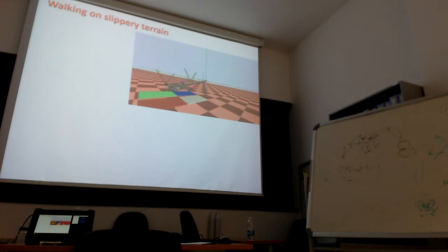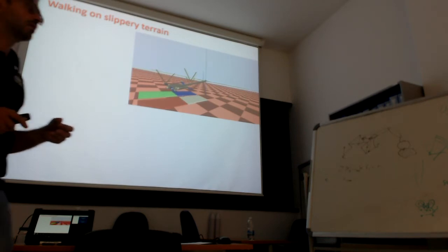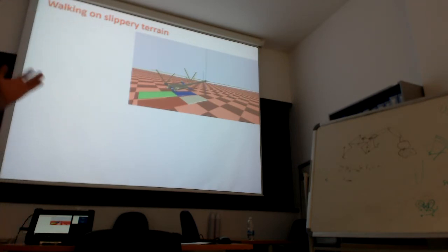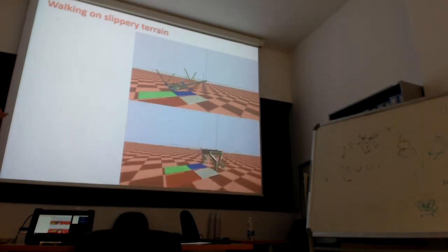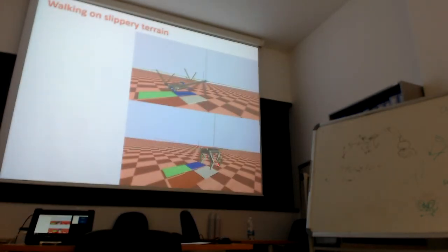So the forces are kind of moving out of the cone because the controller doesn't know that the cone is so small, and so, as long as this happens, the foot starts to slip. Here, the robot has a cone big, then it immediately detects the slippage, a micro slippage, reduces the cone to the real one, and then the force stays inside the real cone, and there is no longer slippage.